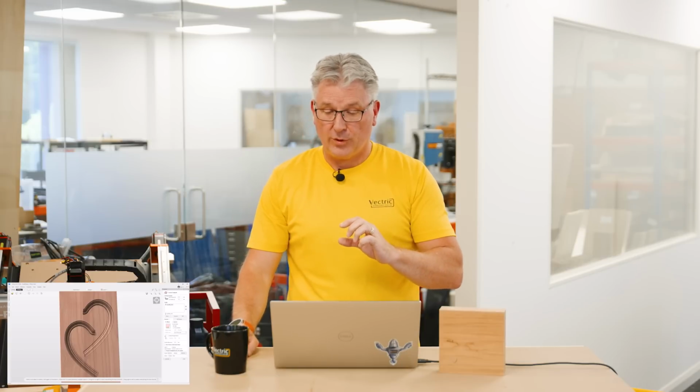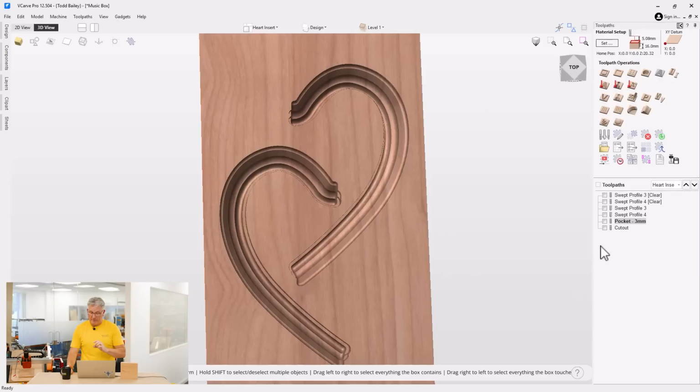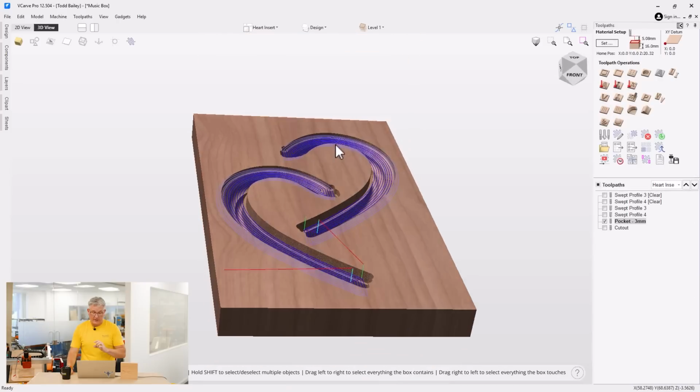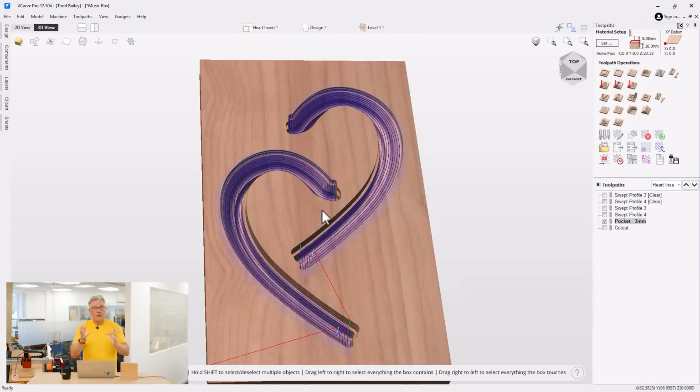So that's what this is for. This pocket will actually go ahead and remove some material above everything. So it doesn't matter what order I run these in, because I didn't realize until after that I needed that one, or that I should have made it. So you can run that first if you want to, and then do your two clearance toolpaths and then your two clearing up toolpaths with your 1/8 inch ball nose.